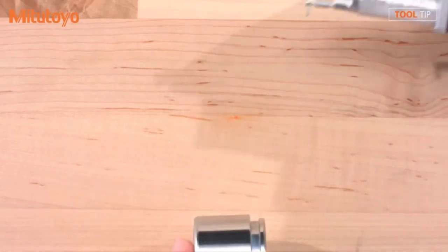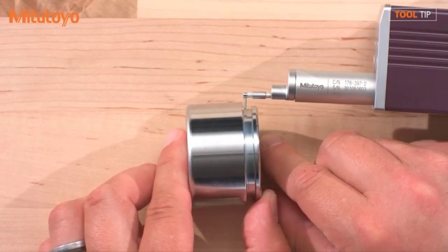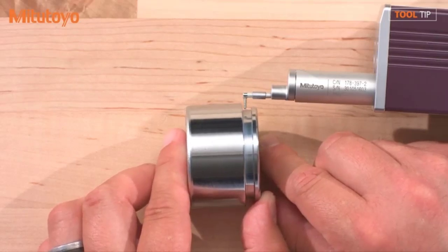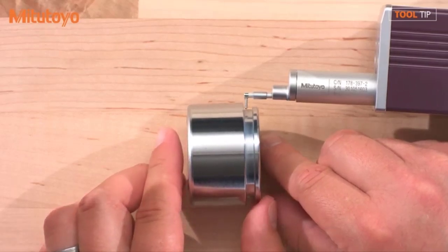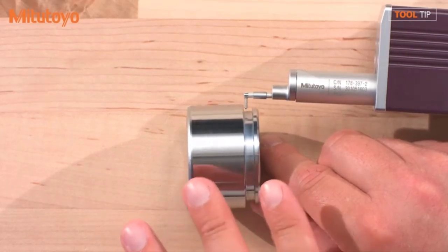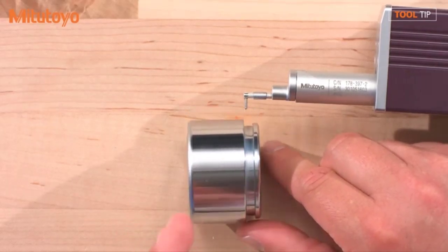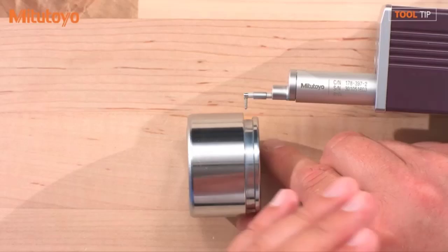However, if I bring my skidless system in, now you'll notice I can easily not only reach the groove that needs to be measured, but I can still have room to measure from side to side along that groove. So let's say that I have a part with a groove that's a little deeper, or maybe a little more narrow. Is there some flexibility in the type of styli that I can use? Absolutely. With both the skidded and the skidless systems, there are different styli that can be used with that system. So if you need to reach deeper within a part or down within a groove, maybe at a little bit of an angle for a gear tooth, we can accommodate for that. There are more styli options available for skidless systems than there are for skidded systems typically though.